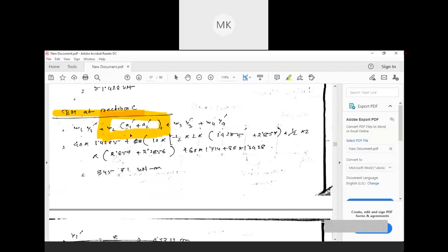Similarly, when we are considering the bending moment, again we need to consider that UDL. For that UDL, we need to find the area. In the bending moment diagram, there will be two areas, A1 dash and A2 dash. Again, by trapezium, we need to find the area of the particular trapezium. We need to put that value. You can find it out differently, or you can simply put it directly in this formula also, as here you can see, it is directly putting these values.